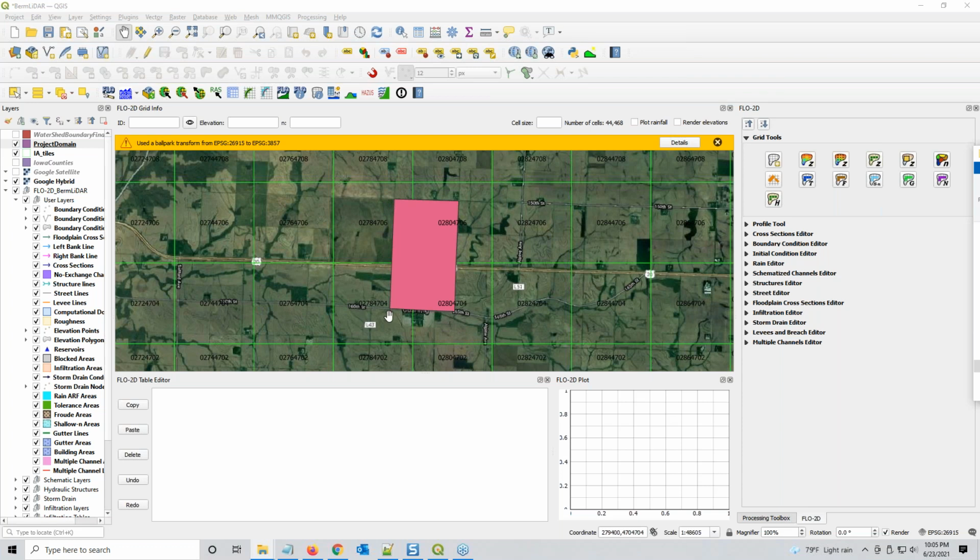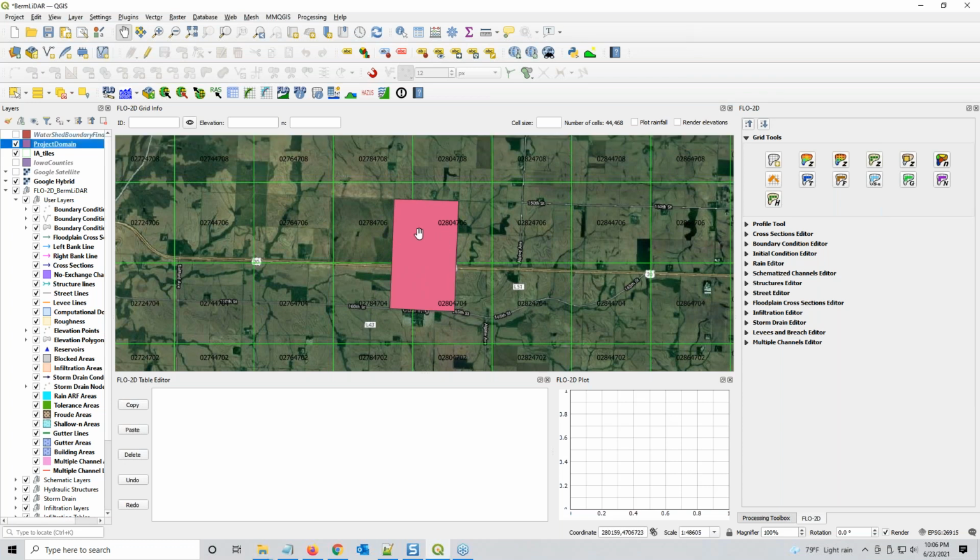So we can actually make some corrections when we process our data to minimize it to just this area. Now, remember this data was in UTM and meters. In the United States, we don't really use UTM or meters on flood studies. We kind of go for state plane. So I'm going to do some of the processing using UTM, and then I'm going to show you how to convert the data to state plane, and then we'll see it again on the state plane side.